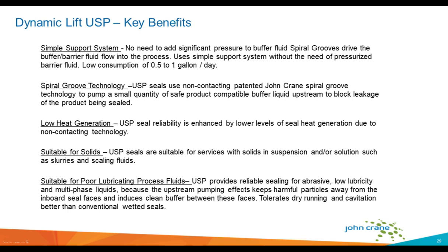The third example would be utilizing your spiral groove technology to seal a liquid with a liquid. So we're using a liquid-on-liquid application of hydrodynamic spiral grooves, and what we call that is a dynamic lift upstream pumping seal, or a USP seal. And it's called upstream pumping because there's deliberate upstream migration or dynamic lift of a lower pressure clean fluid to a higher pressure region within the seal chamber, and we'll talk about how that works in the next slide.